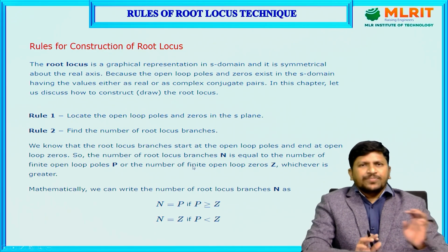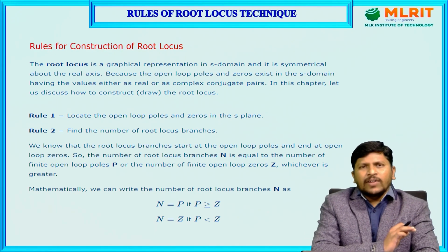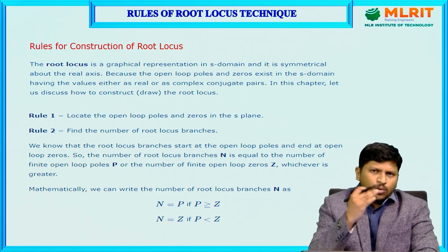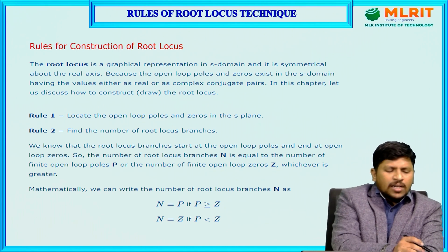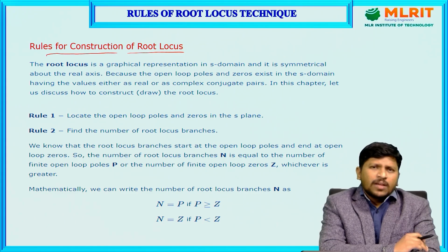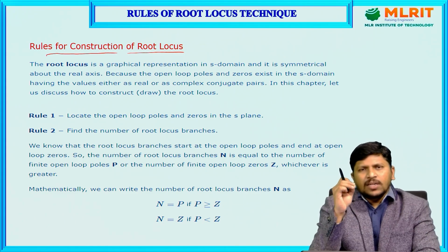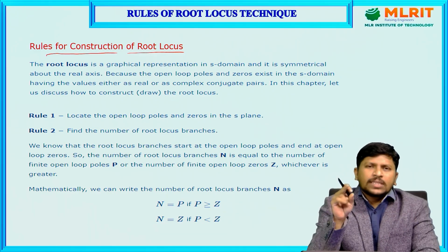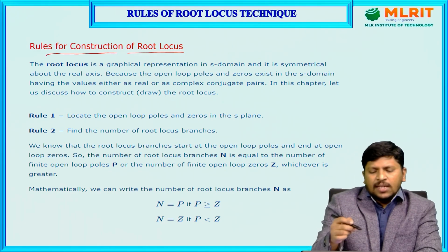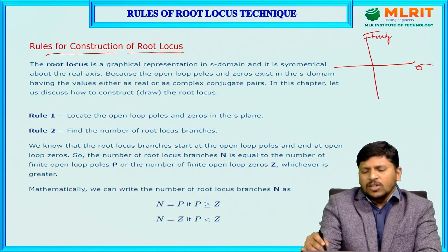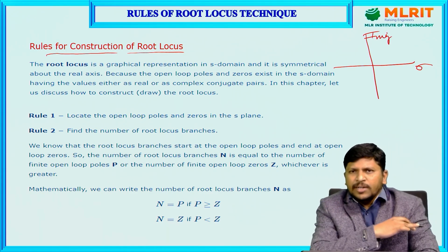Some rules are available for the construction of any root locus, and I am going to explain them now. Rules for the construction of root locus. The root locus is a graphical representation in the S domain. Root locus is always symmetrical about the real axis. Here you see the imaginary axis and the real axis. The root locus is always symmetrical about the real axis.